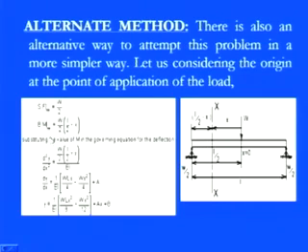Then we can also calculate the bending moment. As for the bending moment sign convention, the point load is on the beam, so this is a sagging position, and for a sagging position the bending moment is positive. The bending moment at the x-axis section is mainly due to the reaction force, so we have W by 2 into L by 2 minus x, this being the distance. So we can simply consider the shear forces as well as the bending moment.